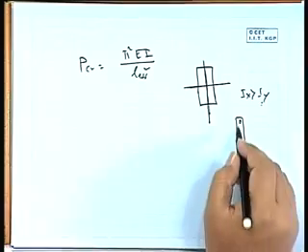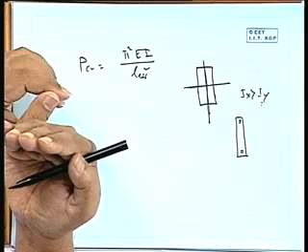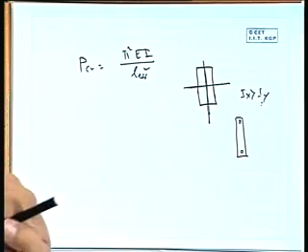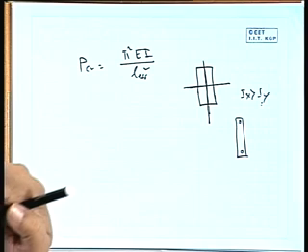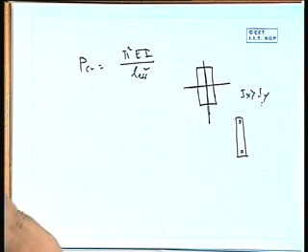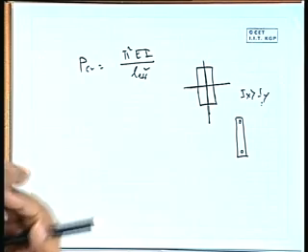Number two, this L effective is very important. Now if there is a plate like this, now there might be a pin. So this hinge is a hinge in that plane. In the other plane, say at the top end there is a support condition like this. There are two plates inside and there is a pin. So it can nicely rotate, but it can't rotate in that manner.